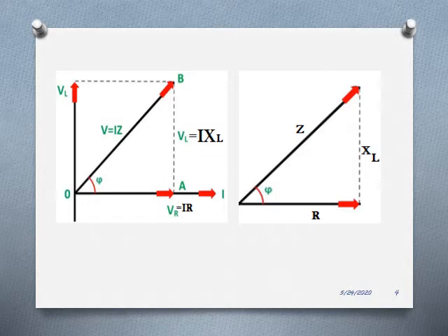That is, the VL term and the current I term have an exact angle of 90 degrees between them. Now, please don't consider OB at the moment. You just consider only VR and VL. Now, this VL, OVL, is nothing but AB. The same value of OVL is AB.